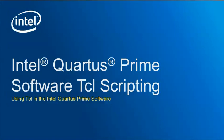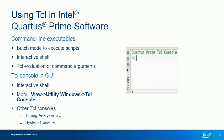In the final section of this presentation, I'll describe ways you can use Tcl and run Tcl scripts in the Intel Quartus Prime software. There are a number of ways that you can use Tcl in the Intel Quartus Prime software. The most common is using a command line executable to run a Tcl script file. You can also use command line executables to run an interactive Tcl shell. Additionally, you can do direct execution of Tcl commands with a command line executable option. I'll talk about these in later slides.